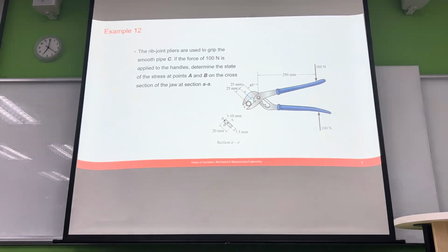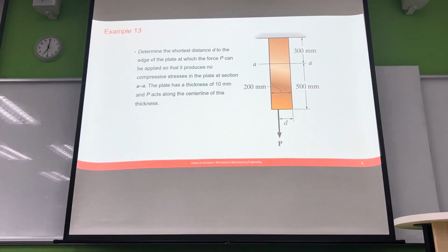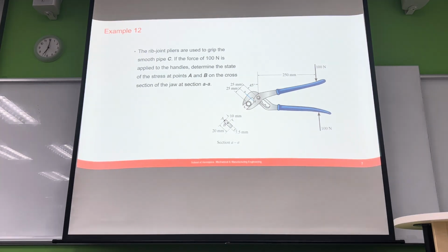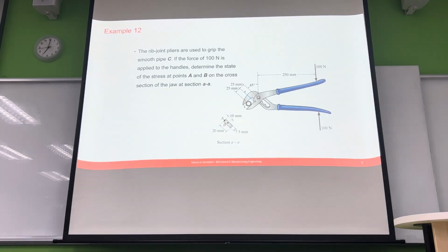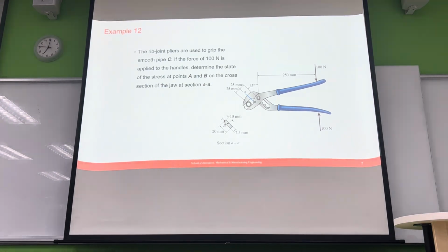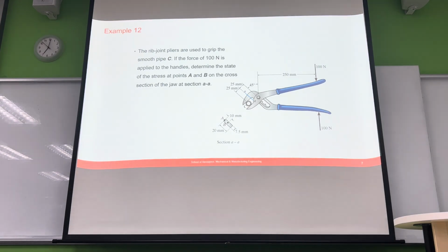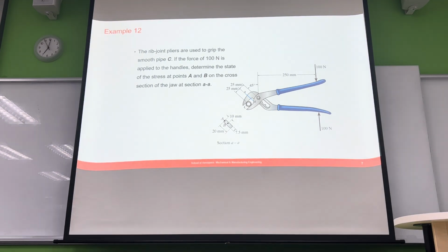So, let's quickly do this problem. Okay, we can do this one. We have a set of pliers, really easy. We're just compressing them here. They pivot about this point here. They have a distance from that point to where you're applying your hands of 250 mil. We're applying a 10 Newton load to it. And then we've put a piece of very hard tubing of some sort, a distance of 50 millimeters away from that pivot point.